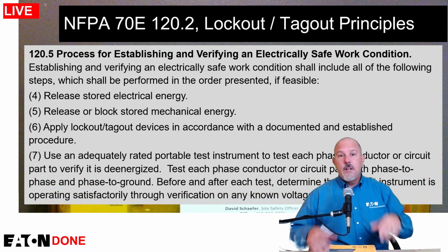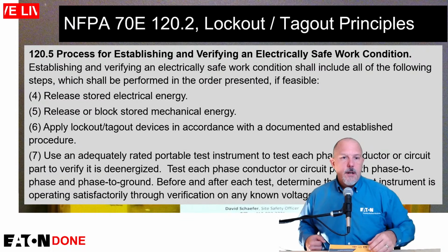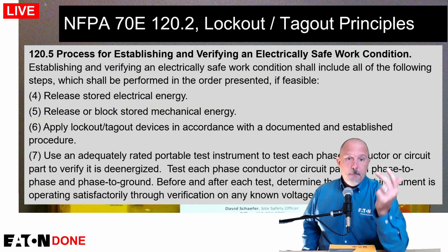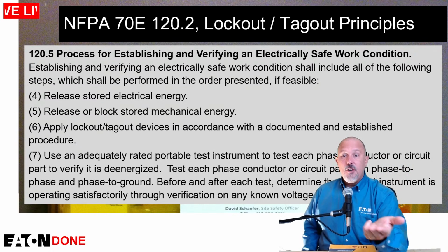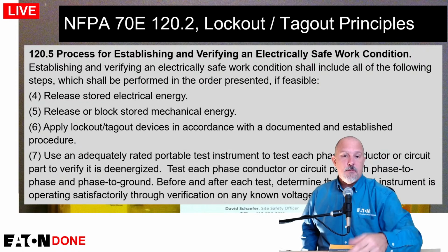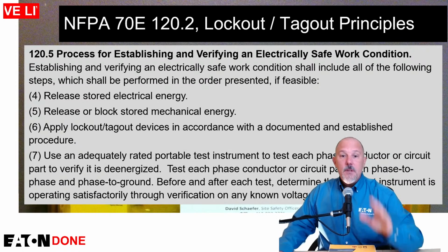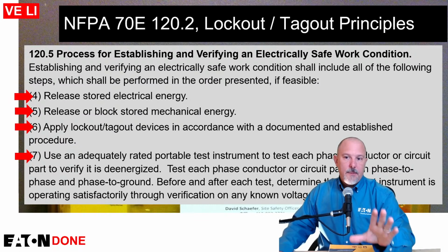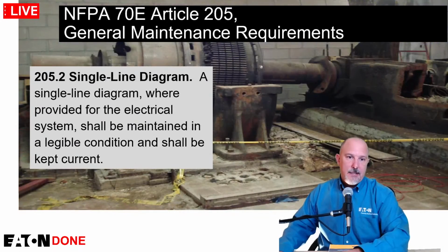120.5, process for establishing and verifying an electrically safe work condition. Release the stored energy. Release blocked stored mechanical energy. Apply lockout, tagout devices in accordance with documented and established procedures. Okay, all of these things, I need good one-line diagrams and documentation, and up to date.